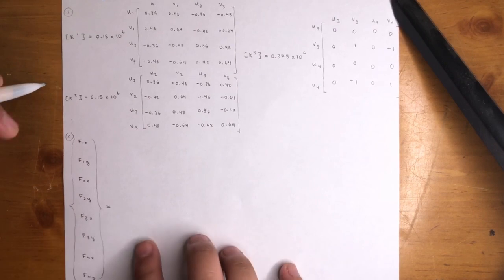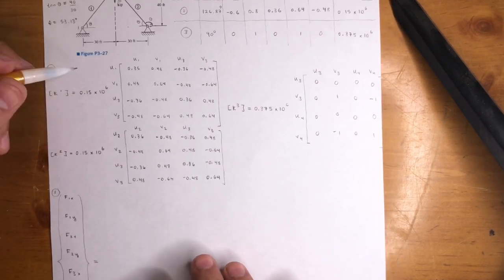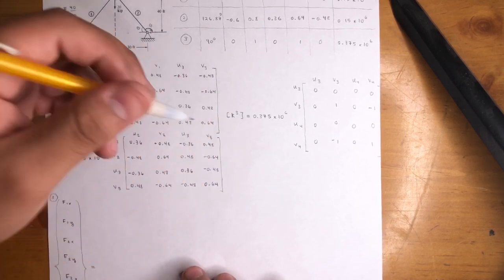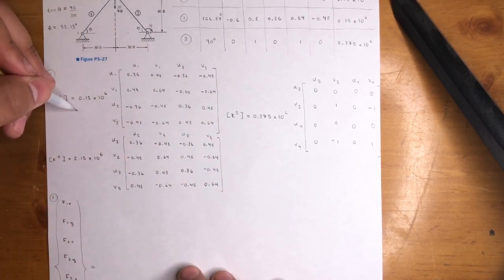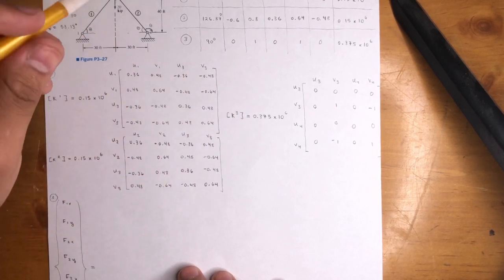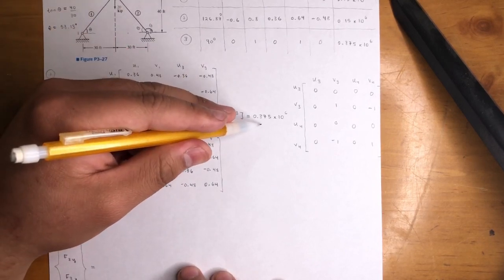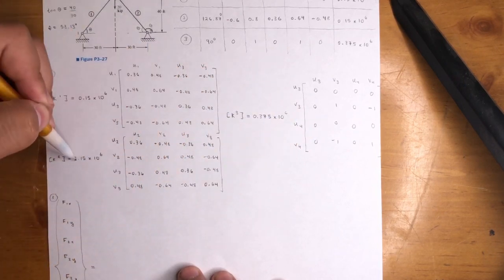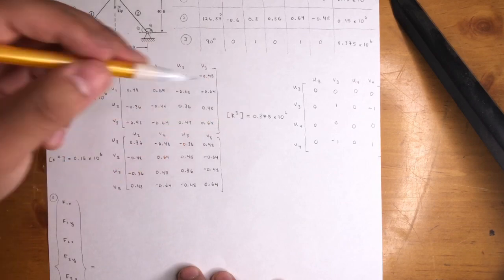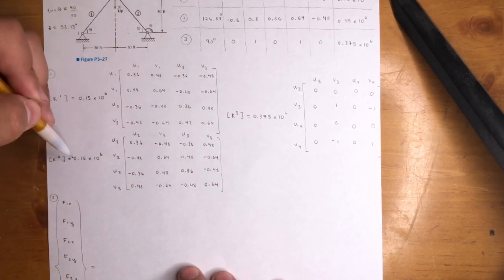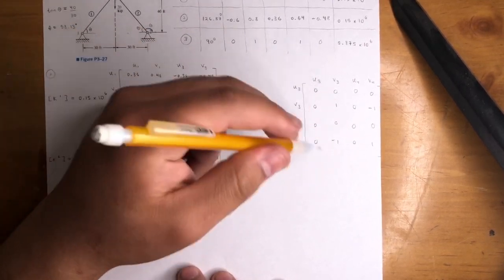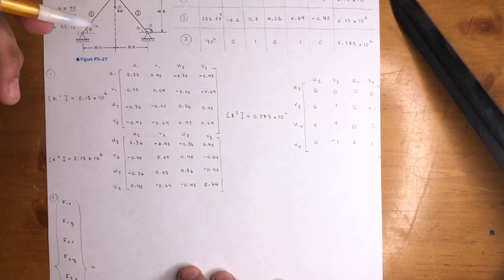All right. So before we continue, we cannot add these matrices, all of them. Normally if they had the same number out here, EAL, we could. But in this case, this one's throwing us off. So now you have 2 options. You could alter just this one in a way that you'll have 0.15 out here, so 0.375 divided by 0.15, you'll get a number, and you could work with that number to fix this matrix up, and you'll have 0.15 all around.